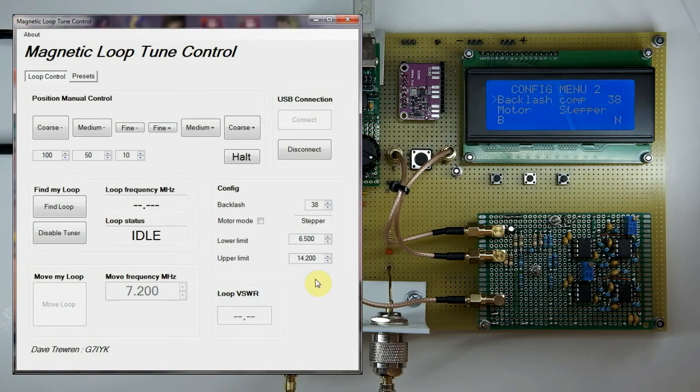a gearbox will have what's called backlash, and that's pretty simple really. There's slop in the gearbox, there's slack in the gearbox, it's mechanical. There's gears and they mesh. So when you reverse the direction of the motor, it takes time for that slack to be taken up. So the motor will be turning, but the output drive won't move for some time until that slack is taken up, and that's called backlash. And it happens when you reverse the motor.